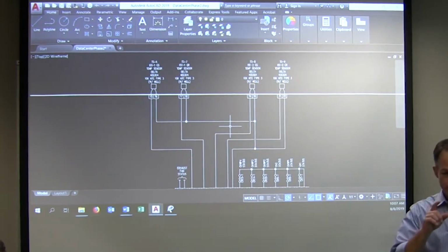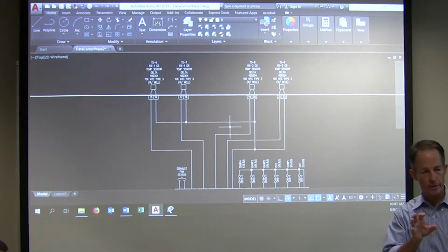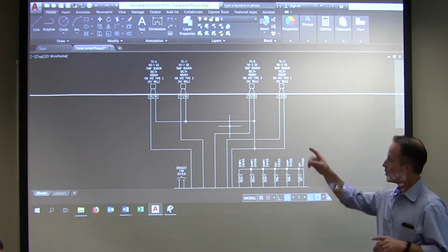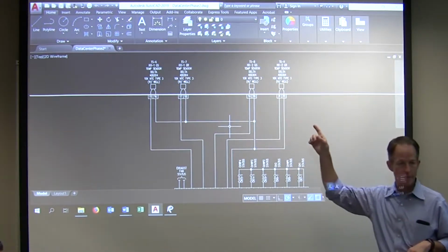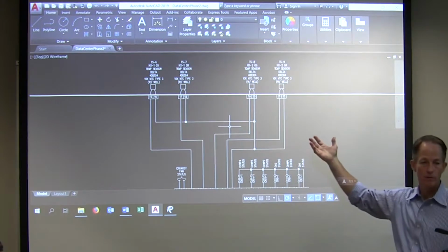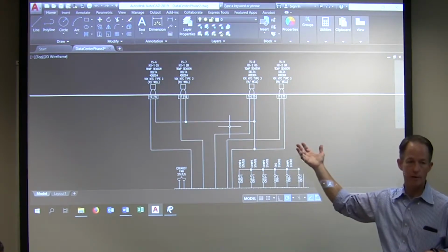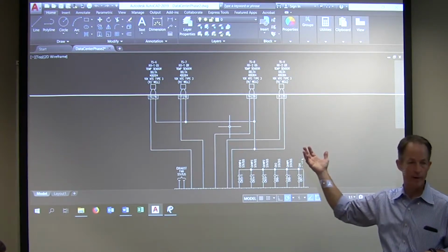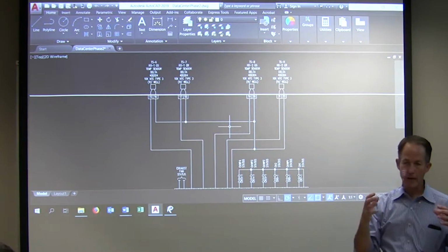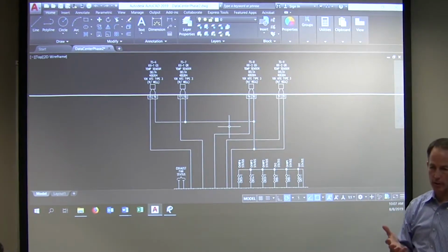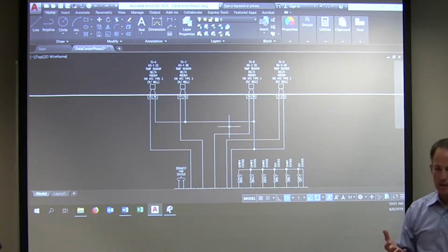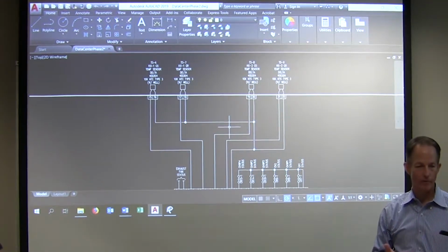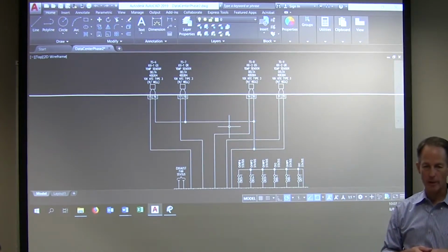All right. We've talked about thermistors, and I want to talk a little bit about RTDs, but I want to ask one more question. Here we're saying a thermistor instead of an RTD. Do we need to be super accurate for glycol or even chilled water? If we're a half a degree plus or minus a degree, we're probably fine, right? We're not doing energy billing off of this. We're not controlling the life safety thing. 45 is going to cool us just about as good as 44 and a half or 44. We're not quite, but it'll help.